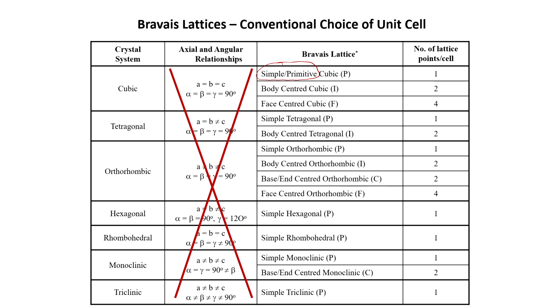The one that I have crossed out does not mean that if I have a cubic unit cell where I take a cube as the unit cell, then these relationships would not have to be obeyed, but these are not the basis for it to be defined as a cubic unit cell. Now, let us take some examples and try to understand why I do not have an end centered cubic. An explanation is given in many of these publications and books, and most of the time one finds that the explanation is actually wrong. So, let us first look at what kind of explanation is given.